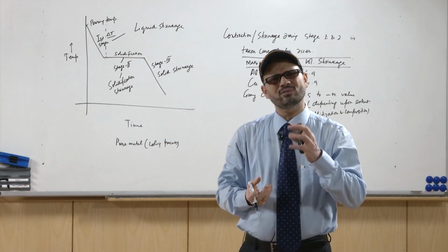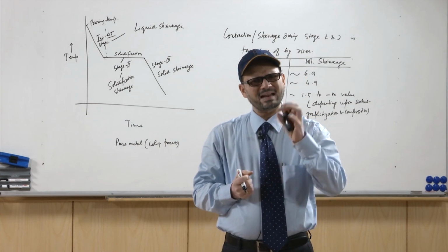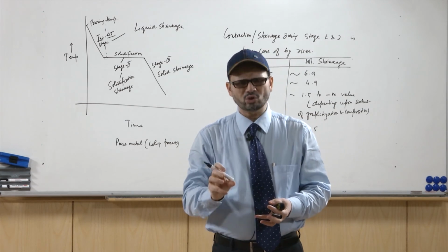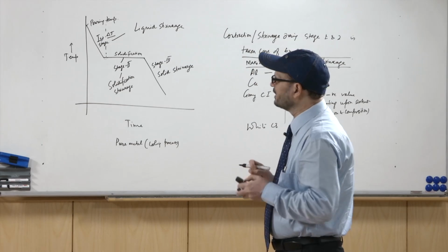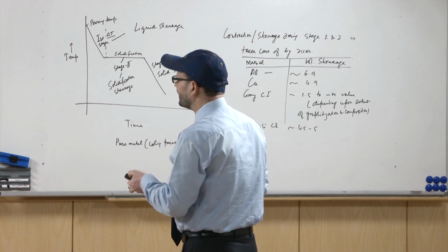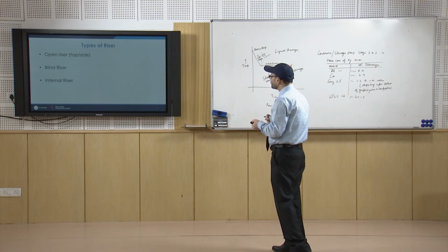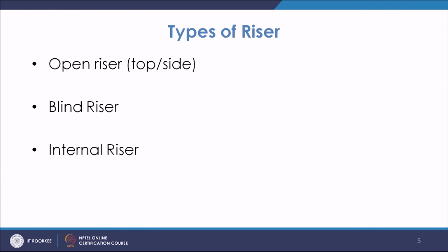Another is the force of gravity. So, under gravity metal goes inside the cavity. Now, if in your top riser, the top portion is not in the liquid state and gets solidified, in that case this atmospheric pressure will not work, and even because of the gravity the liquid metal will be pushed towards the casting, and a vacuum will be created.